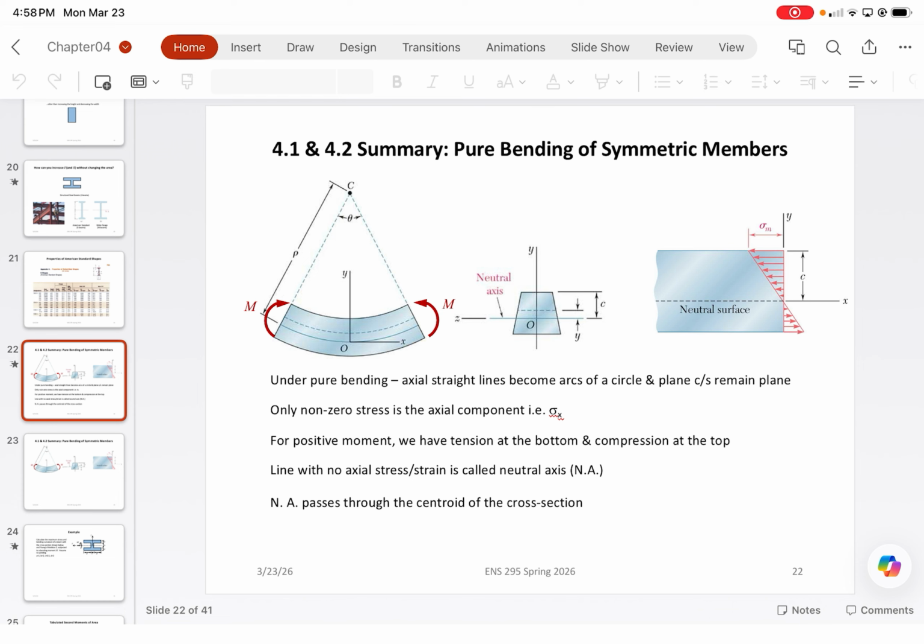Yes? Do we get the dimensions? Well, this is not what we're going to be using. Okay. I actually asked if Andres could make it. So once he comes up with an idea on what dimensions are likely going to be needed for it, we can work from there. But right now, you should be able to do a preliminary design assessment, just assuming 70-pound point loads, because that would probably be the most conservative load case you can imagine. It's basically an infinitesimally small area, so the force is very concentrated versus distributed over a certain region.